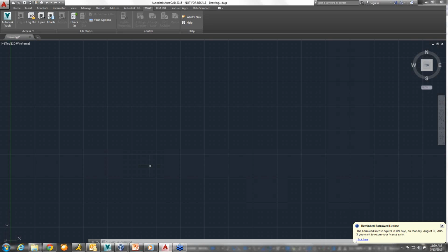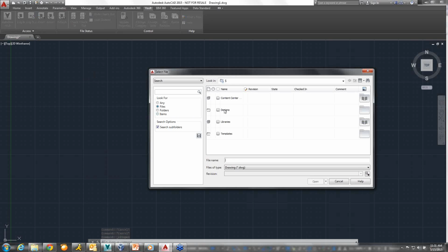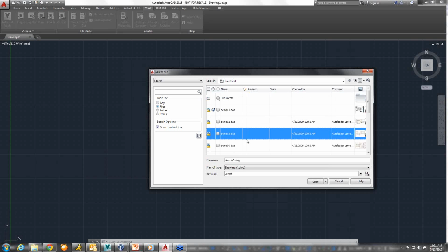Now if I go over to AutoCAD itself, I can see the Vault ribbon that's inside of AutoCAD, inside of Civil 3D, inside of Microsoft Office. So instead of having to use the Vault client to do functions, I can do most of my document management work from inside AutoCAD. So, instead of finding files here and opening them, I can just hit the Open from Vault command here, and I can browse my Vault to find files that I want, and then open them read-only, or open and check out.